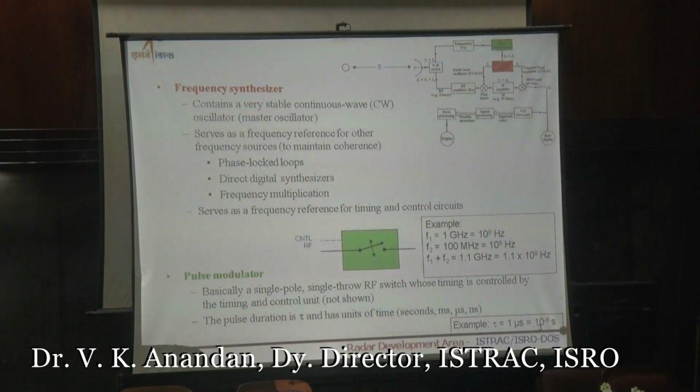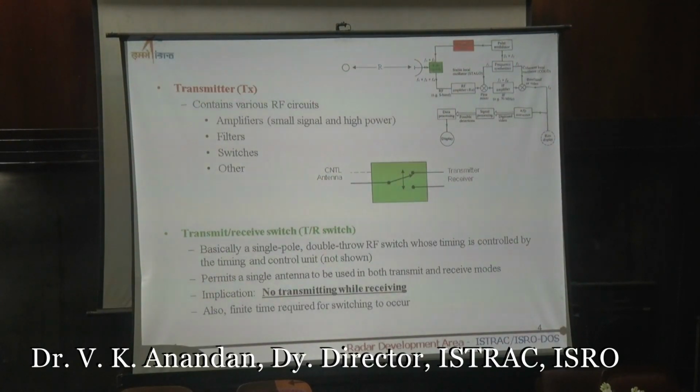So from that point we will have signals, and it has a pulse modulator also as part of it. What it means is you have a signal F1, a stable coherent oscillator. Then it is combined with an additional signal, which we call the IF, intermediate frequency, and goes to the transmitter. Finally, it will come to the TR switch, which is explained as a duplexer. You can look inside a simplified form of the diagram where it finally transmits.